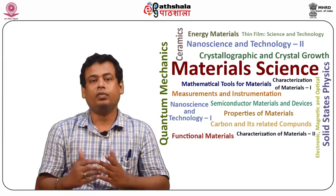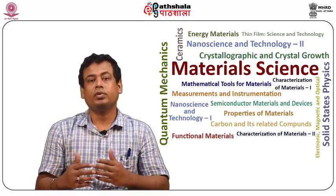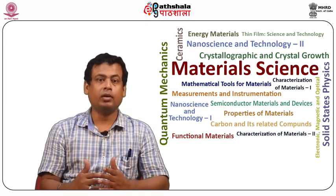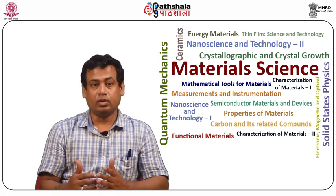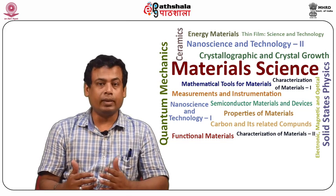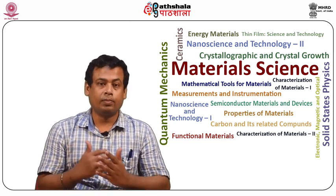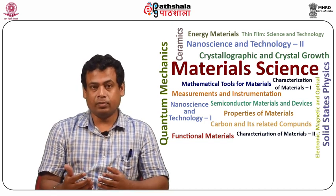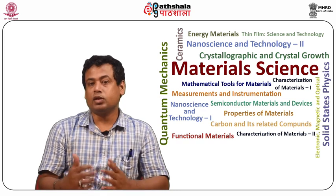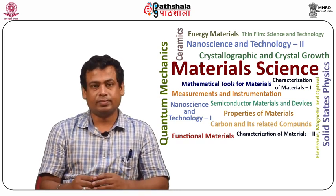The etching of unwanted material or metallization of new materials is pursued with the patterned resist on the surface, followed by the resist cleaning from the surface of the substrate to fabricate the nanostructured materials or patterns.